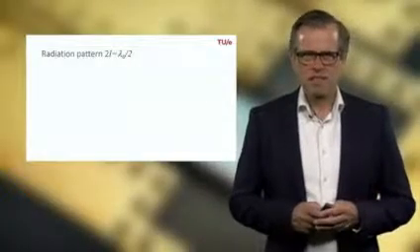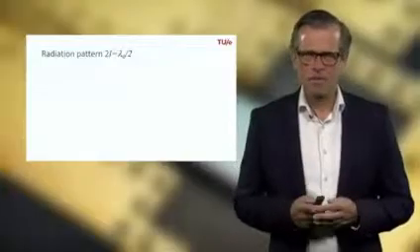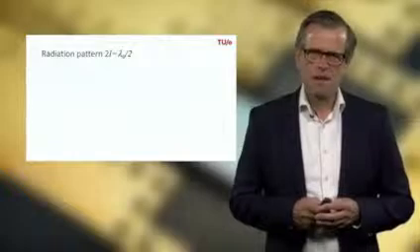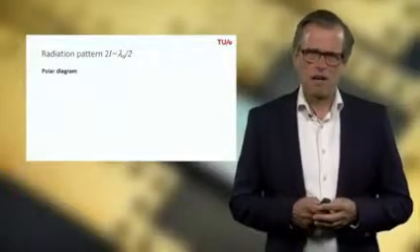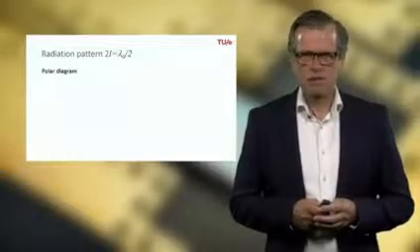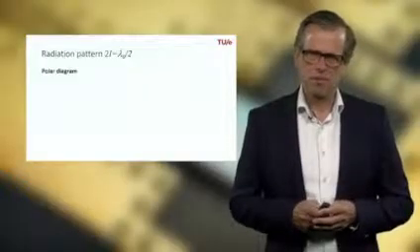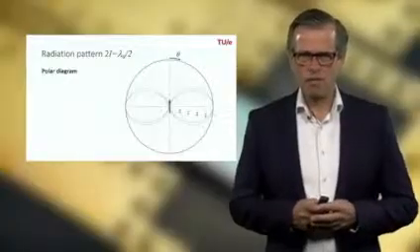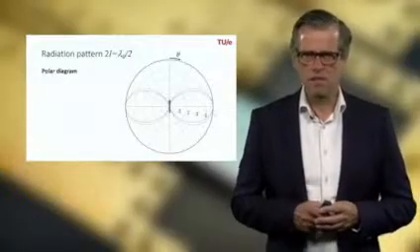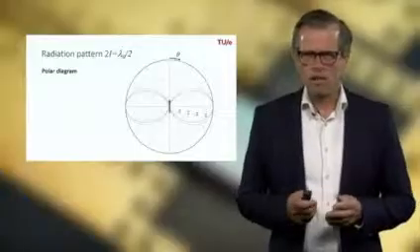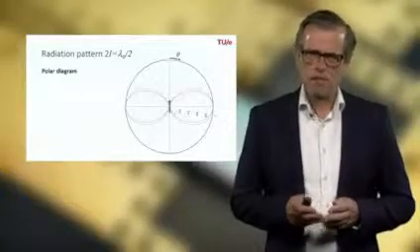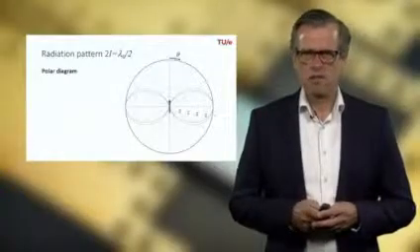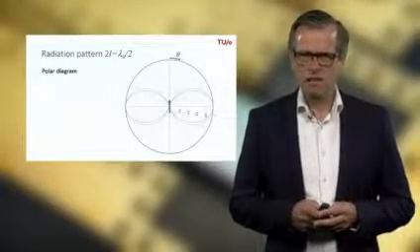And first consider a dipole with a length of a half wavelength, which is the most commonly used dipole in applications. Let's consider a polar representation of this radiation pattern, as we also used for the electric dipole. Doing that, we get this plot. And the half wavelength dipole is positioned in the middle, as indicated by the blue arrow in this diagram. So it's vertically directed, and you can see that the radiation maximum occurs at an angle theta of 90 degrees.